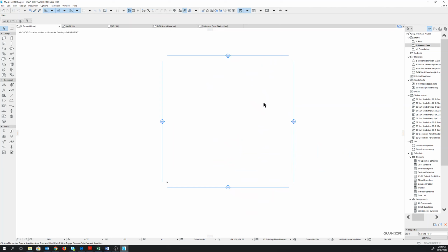However, we need to draw on the site boundaries and contour lines that we created in our 2D working sheet. To do that, go to your navigator box and right click on the drawing sheet or the worksheet that we created, which is W01 site. Right click on it and choose show as trace reference.